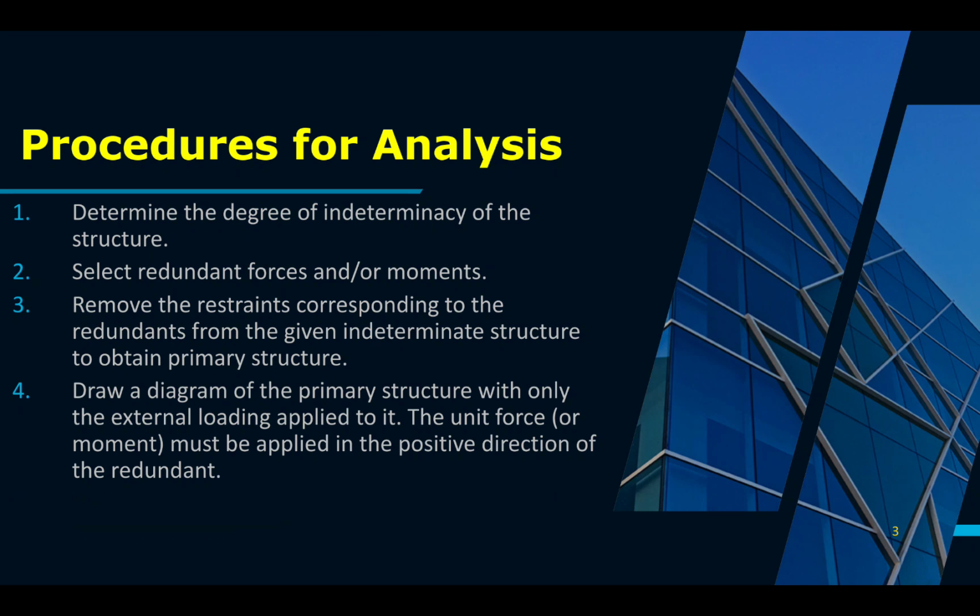And then another is to draw a diagram also for each redundant. So draw a diagram of the primary structure, the original structure with only the unit value of that redundant applied to it. The unit force or moment must be applied in the positive direction of the redundant.